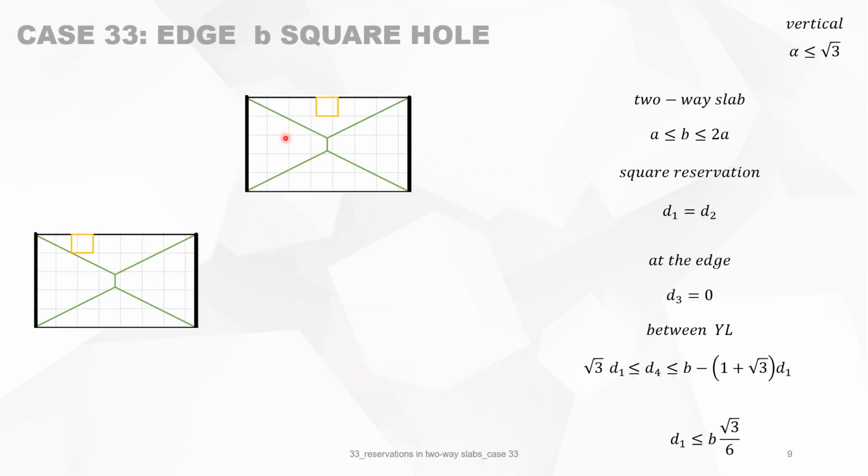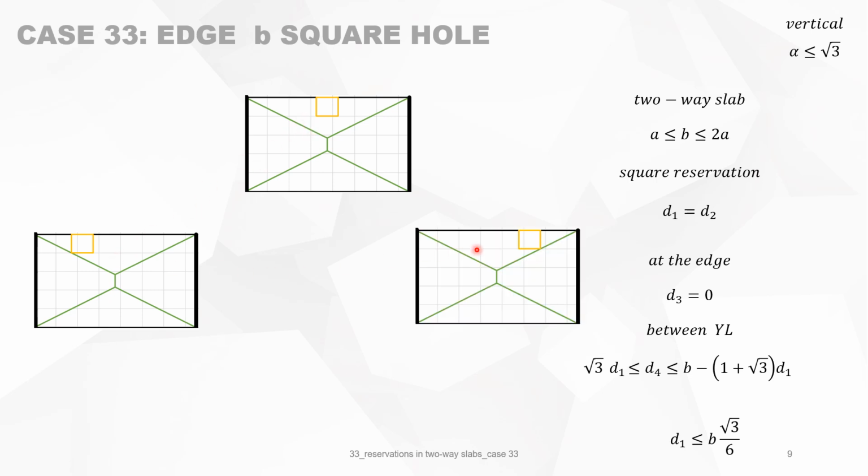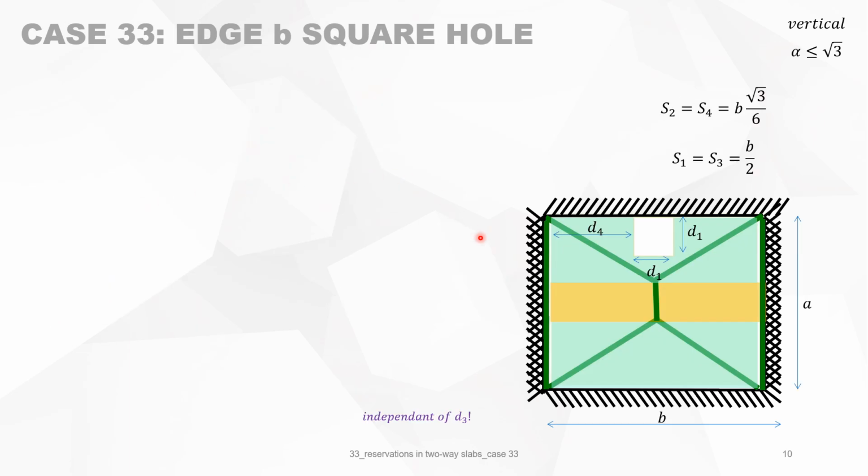Now you will see here how it will look. It will go like that with the values of S and the limit on D3. D3 is this distance. We can now calculate the work done by the external forces, which is, for instance, for the rectangular section, B times this piece, which is A minus S4 minus S2, and multiplied by delta over 2, which is the mean deflection.